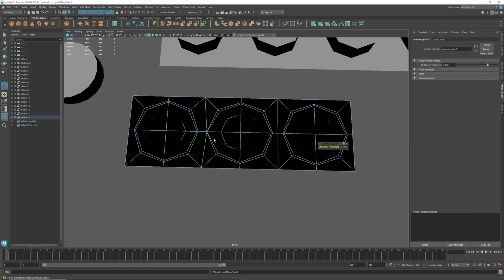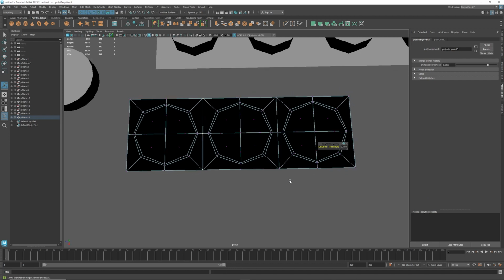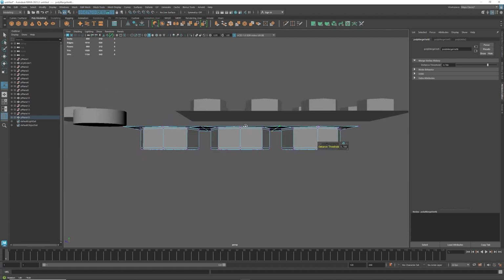You'll notice that something else was grabbed and it screwed up, so we can undo that, and we're just going to hold control and unselect those 2, shift right click, merge together, and we're going to basically merge those down to that point. So do the same thing over here, and you'll notice I have 6, hit G, and it merges it to 3. So we're good with that.